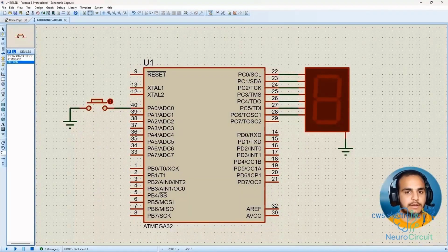However, we currently have a pull-up mode enabled, which is a feature that is not commonly utilized in many simulation projects that one might encounter. In the simulation, everything works perfectly and gives the right results. But then, in the real world, they see that the button doesn't work at all and picks up noise, and only then do they realize what should actually happen. And for example, this is one of the important differences between the simulation world and the real world.